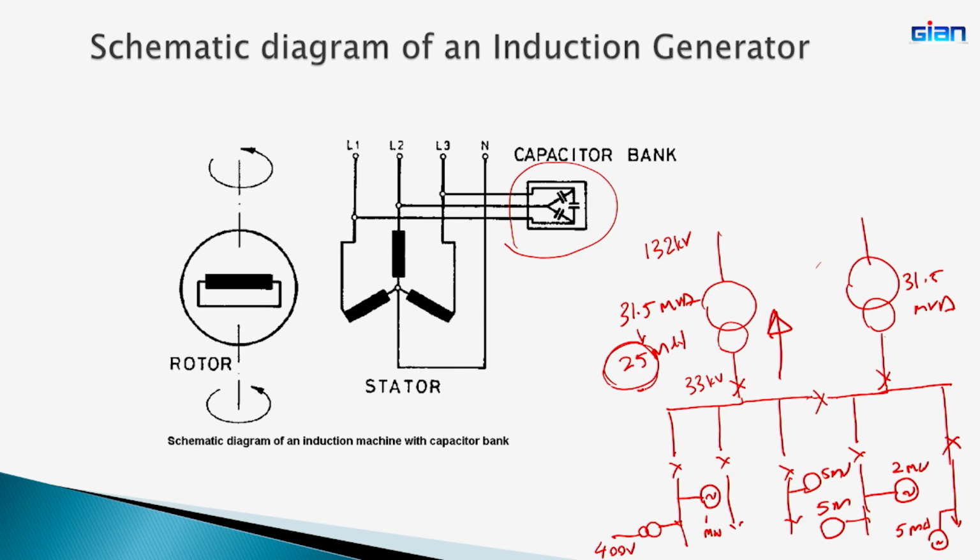Therefore, utilities will have a limit when you have a 2 transformer system, each having 25 megawatt. The addition of all the generators has to be less than 25 megawatt, right. That is, together mini hydro, solar, rooftops, all together they will not be allowed to exceed 25 megawatts.